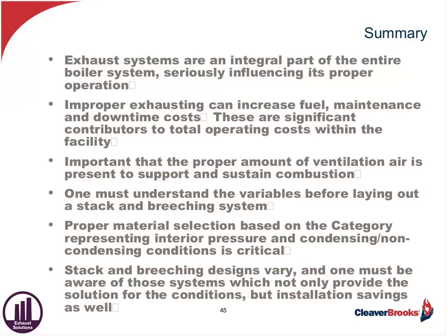In the very beginning, we have to make sure that the boiler room itself has enough ventilation air. What we use as a rule of thumb is 10 CFM per boiler horsepower: 8 CFM for combustion and 2 for ventilation. Not to keep you comfortable, but to make sure that the room does not go negative, or does not go positive, I should say. We want to make sure that we do not go positive in the boiler room itself.